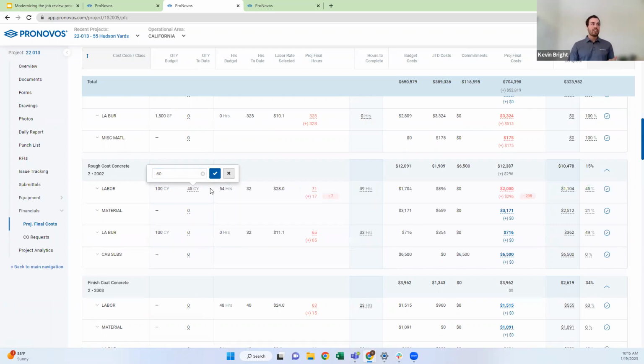And the reason that I think using your quantity complete is kind of the gold standard is twofold. One, it's going to be the most accurate, right? If you're actually counting what you've gotten done on the job site, that's going to be way more accurate than trying to figure out what your costs are. And the second reason is you can start to leverage production rates. And when you start using production rates, it really gives you a lot of insight, not only into how you're performing on a job, but also some corrective action you can take.